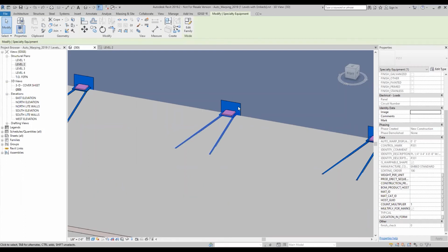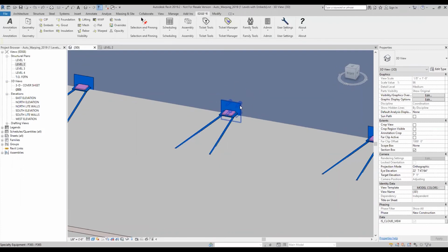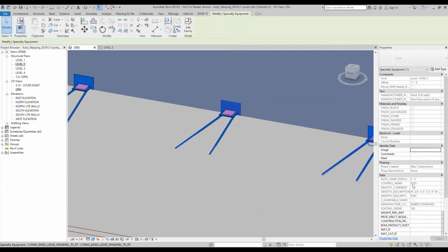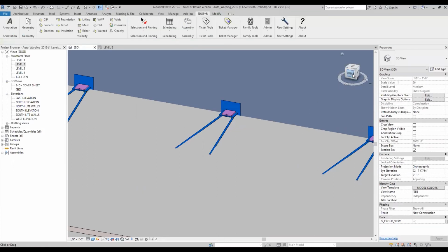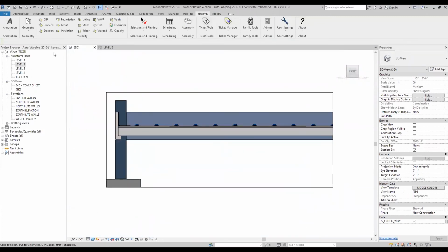The spandrel plate would need to have an offset value written to it so that the original plate would be moved to the correct location within the spandrel to mate up to the warped double T during erection. So, the spandrel plate would need its is warpable shape parameter set to false so that a direct shape would not be created for it, and you would instead want to control its offset with the auto warp displacement parameter. This will allow auto warping to offset the spandrel plate to the correct position relative to the warped double T that it will be connecting to.